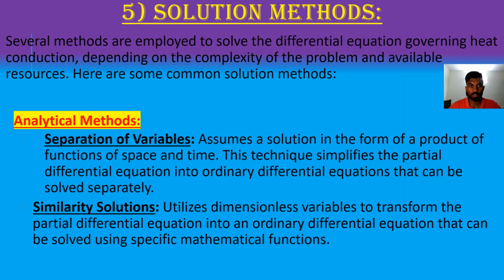Let's know about solution methods. Several methods are employed to solve the differential equation governing heat conduction depending on the complexity of the problem and available resources. Here are some common solution methods. They are analytical methods. Separation of variables: assuming a solution in the form of a product of functions of space and time. This technique simplifies the partial differential equation into ordinary differential equations that can be solved separately. The second one is similarity solution. It utilizes dimensionless variables to transform the partial differential equation into an ordinary differential equation that can be solved using specific mathematical functions.